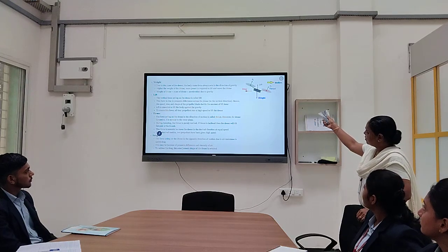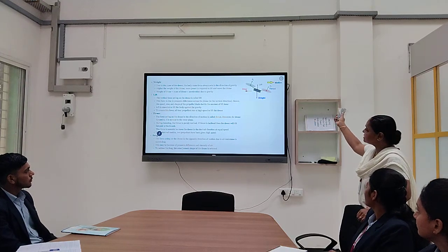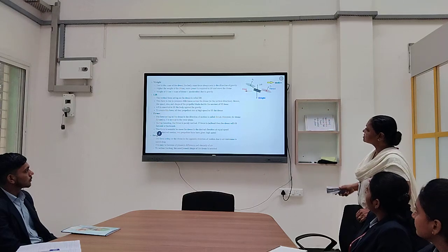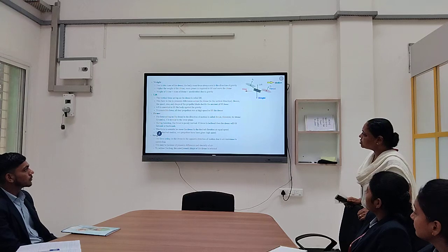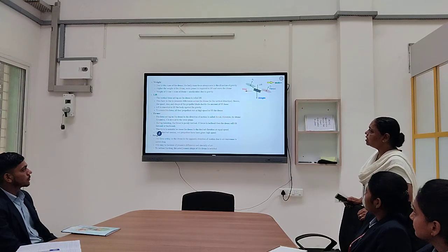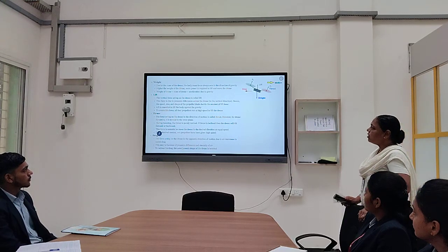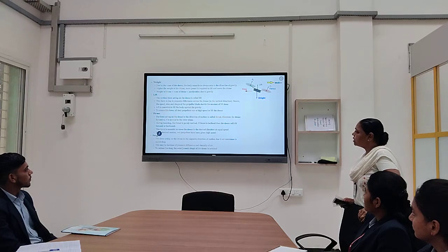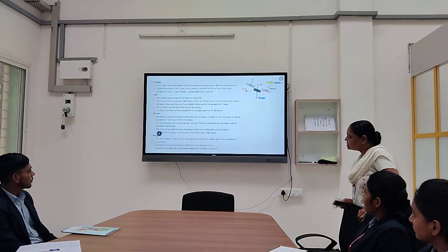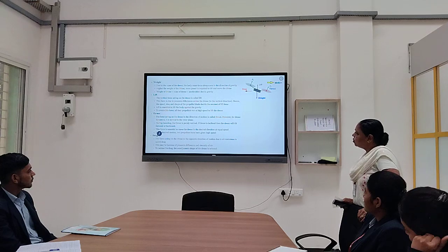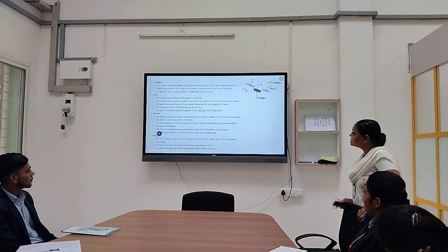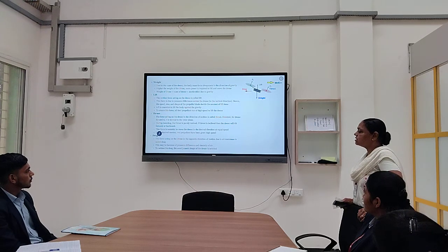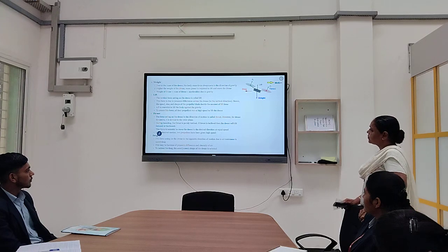Direction of motion. See, motion of the drone is to the right side, and that force is acting. That is the thrust. However, for drone dynamics, it is normal to the rotor blade. During hovering, the thrust is purely vertical. If thrust is inclined, then the drone will tilt forward or backward. This force is essential to move the drone in the desired direction at equal speed.